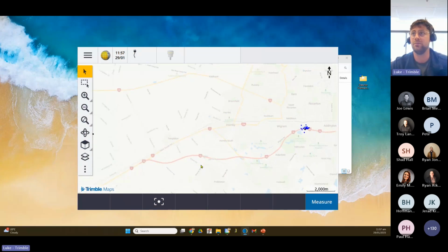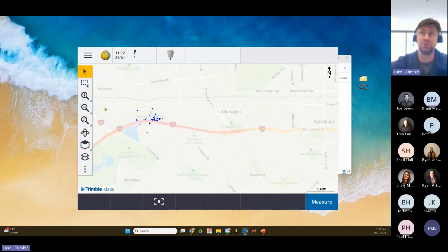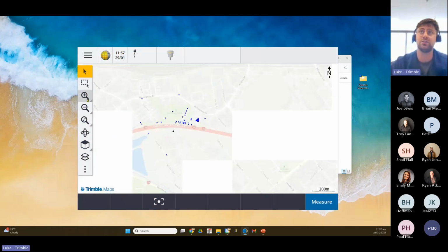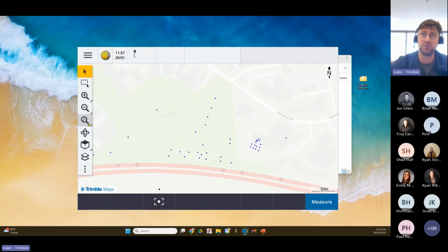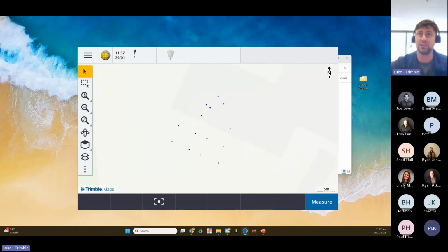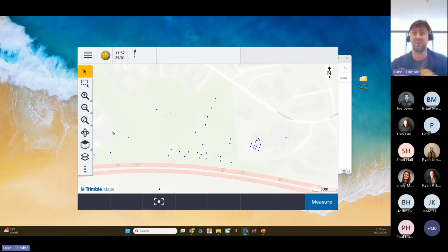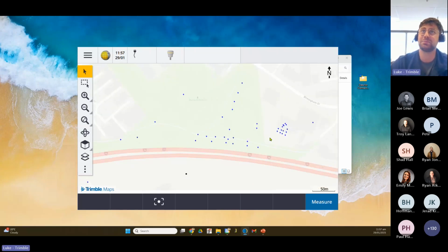But if you want to set your own user extents, you can zoom into the user extents that you're working at, tap and hold that zoom extents button and click set user zoom extents. Now every time you want to go back to the user extents, it goes to that previous user extents that you just defined, not way back out to the project. There's one tip. That's probably one of my favorites.